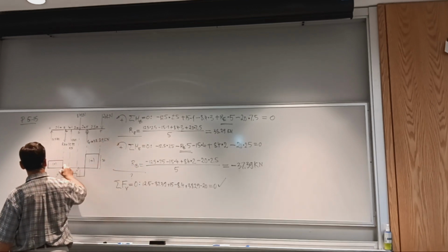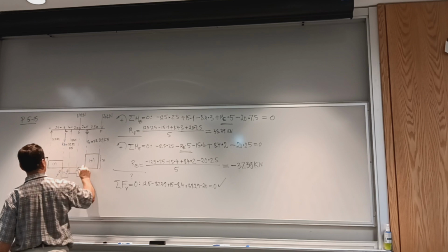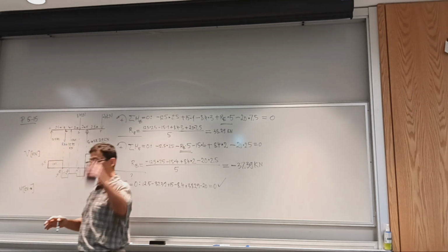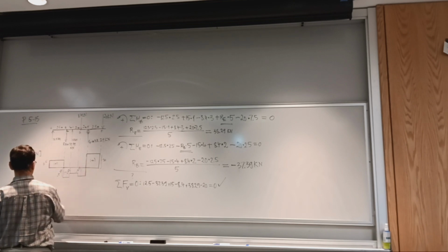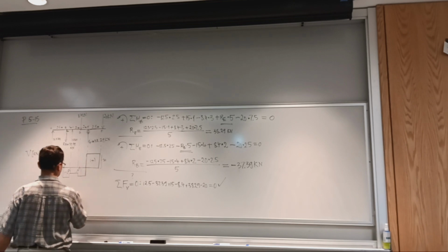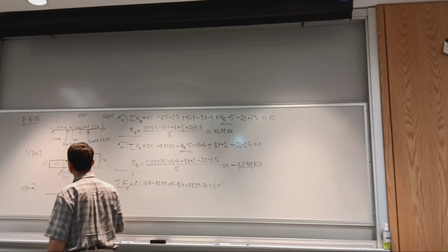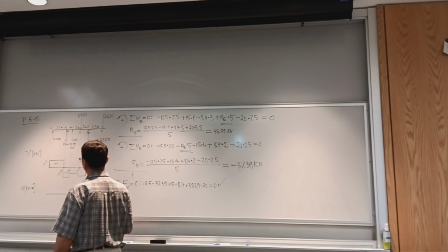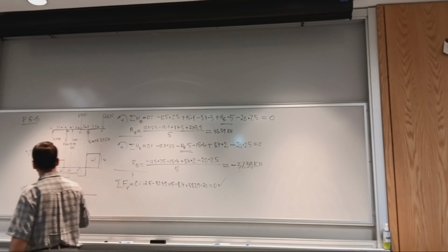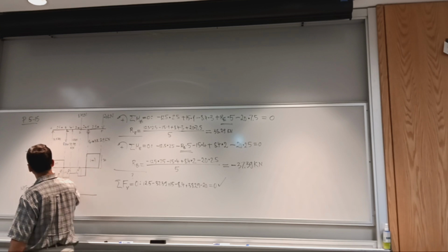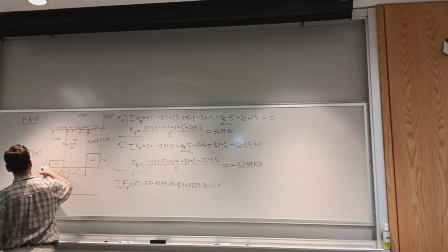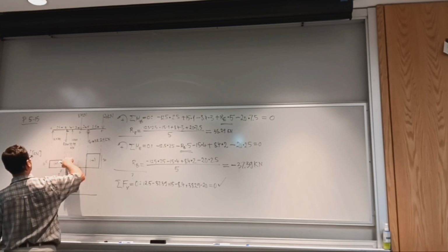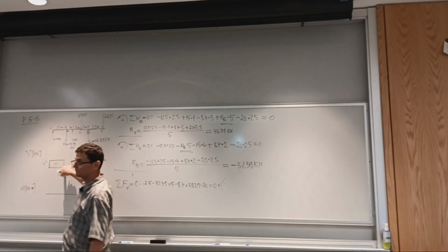I'm seeing 2 zeros on the shear diagram, so I'll have 2 points of extrema, maximum and minimum. So I'm showing the diagram evenly spaced on my x-axis. It begins with 0 moment, and it grows linearly with a slope of 12.5 up to point B, where there is a maximum.